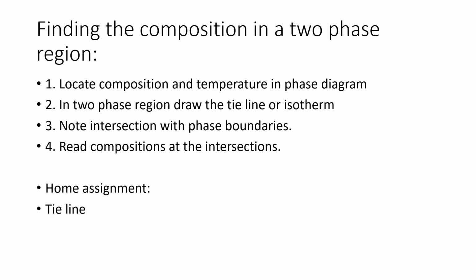This is your home assignment: how to find the composition of different elements at different temperatures with the help of the tie line and the lever rule. Usually we use the lever rule when we locate the composition and temperature in a binary phase region.